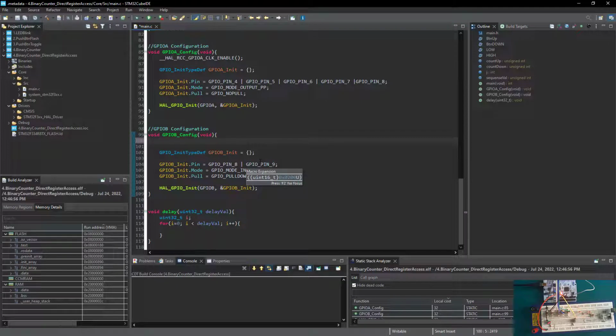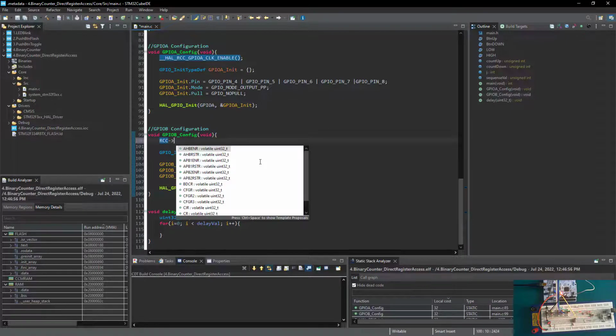So I'm going back onto my code, and I need to call now the reset control. So that will be RCC, reset clock control. And then I'm just going to point the arrow and wait for the IntelliSense. Now the IntelliSense here for the GCC ARM compiler is already seeing that, okay, you want to access the registers onto that RCC. Well, here are the list of registers. Now, which one do you want? You can just go and look for the one that you're looking for. Now, I'm taking the top one.